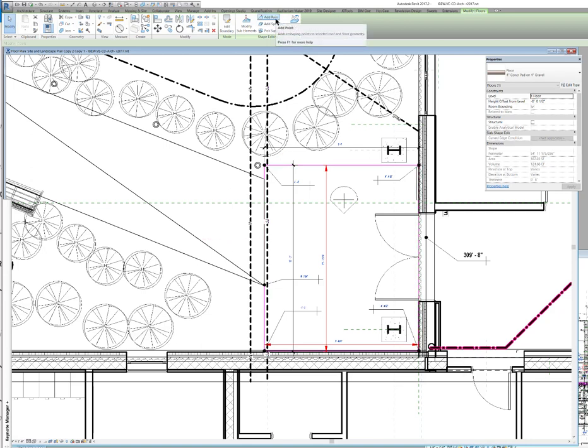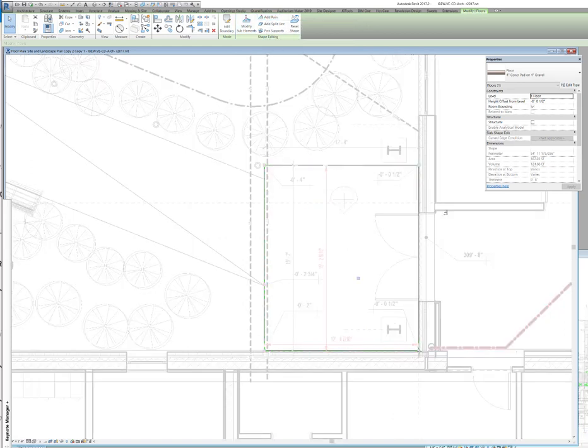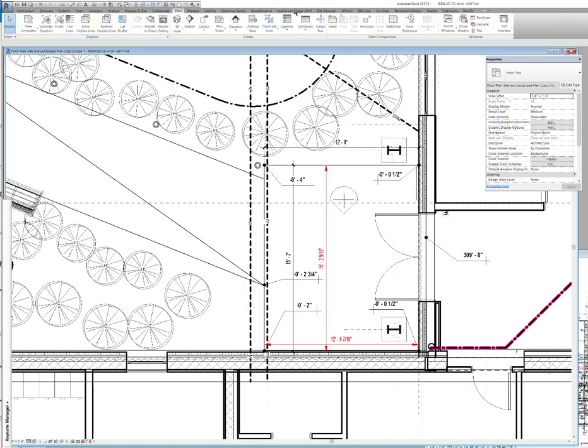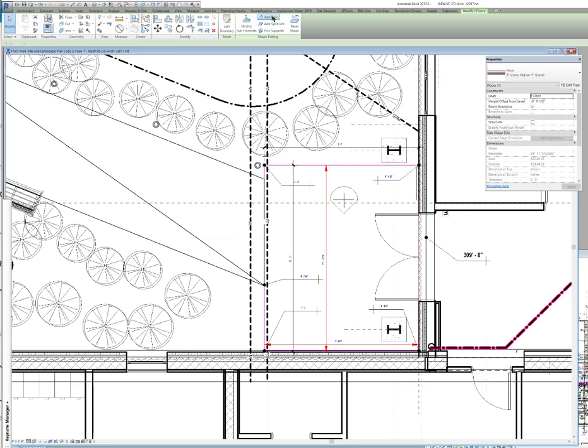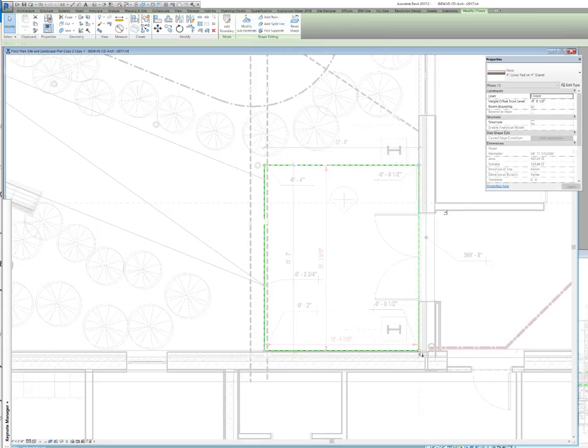So in my case it's pretty simple, and all you need to do is go into the add a point. So this corner here, I'm sorry, not add a point, modify sub-elements. So this point here should be at 0 because that's at 0 from a ½ inch down, and then I want to go from that point down 1/8 of an inch a foot, 12 feet, that's 1.5 inches. So this should be at -1.5, again from a ½ inch down, that's where I started.